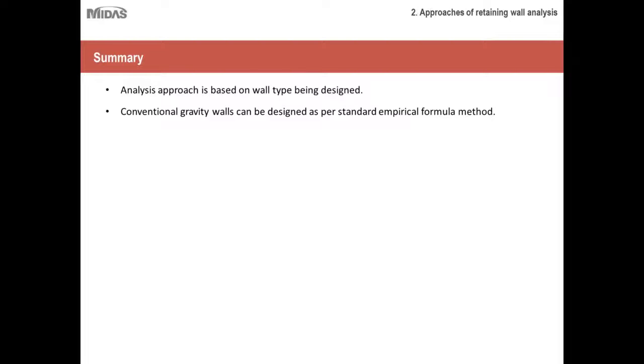So basically for conventional gravity walls, you can design as per the empirical formula method that we have been learning and using in school. For MSE wall, we need numerical analysis for the estimation of deformation and stresses during construction.